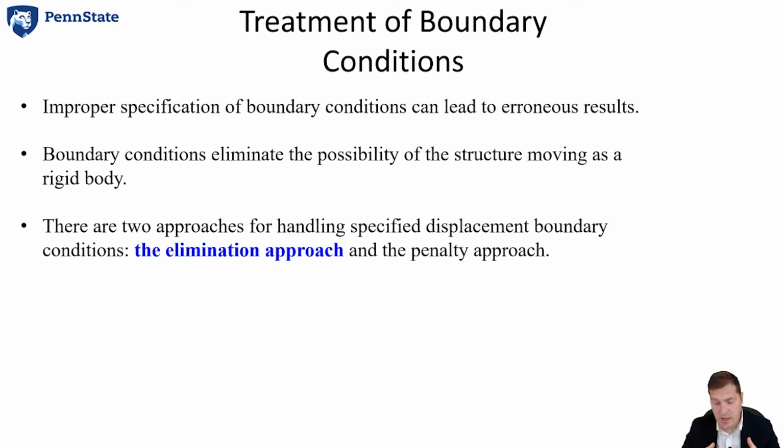And what you notice is that if you don't do that, sometimes it's a hard problem to debug because you have this rigid body translation. Your tools like CEE and the visualization module don't always show your X, Y, Z coordinates, so you can't really see that translation, which makes it tricky, especially in the static case, but it has moved through space. And a lot of times in those cases, it does not converge, so it can be a hard problem to debug. So you always want to think about how you can constrain rigid body motion.